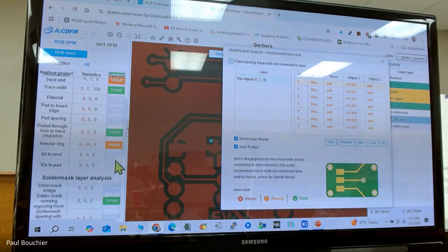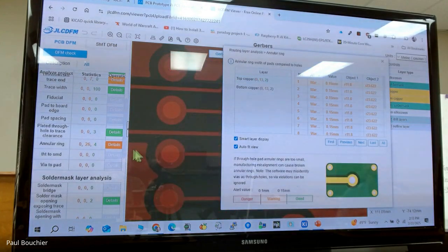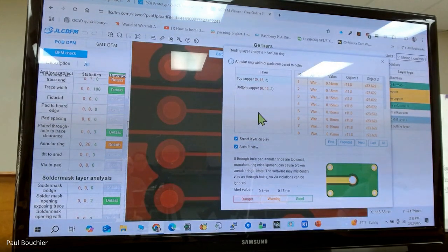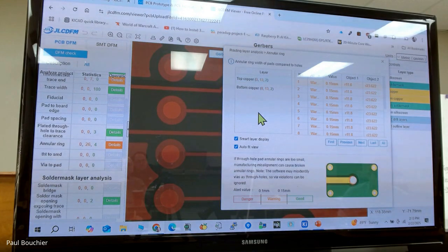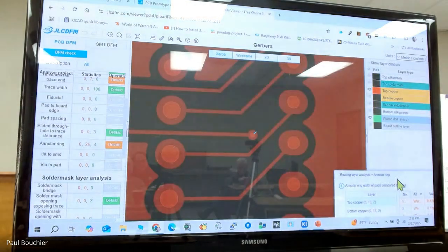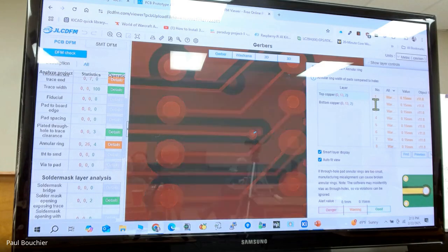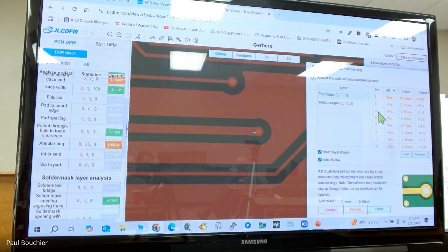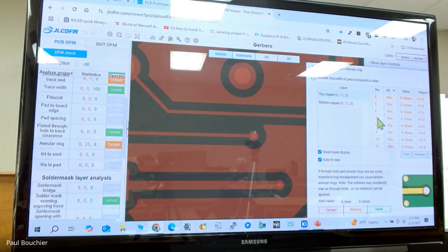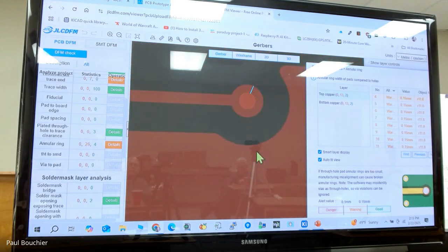Okay, here's a bunch of blanks. Let's see what those are for. It's saying there's a through hole pad, 26 of them. That sounds like the footprint on one module might not be right. Could happen. I don't know what that is. Look at the second one. I don't know what that is either. Looks like the vias might be defined as something that JLC PCB doesn't like.